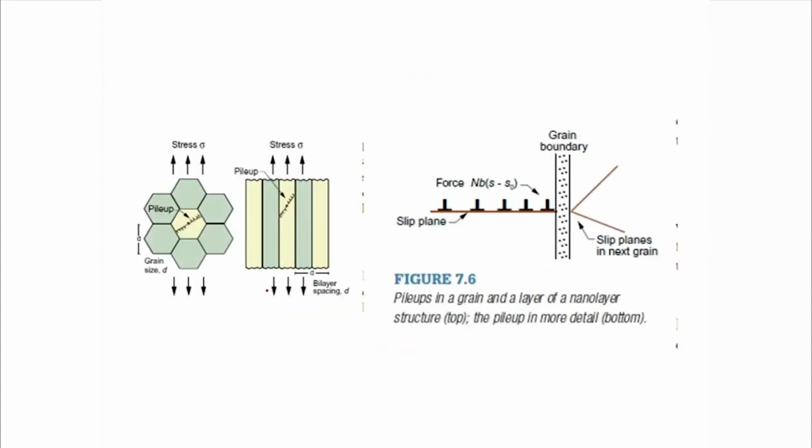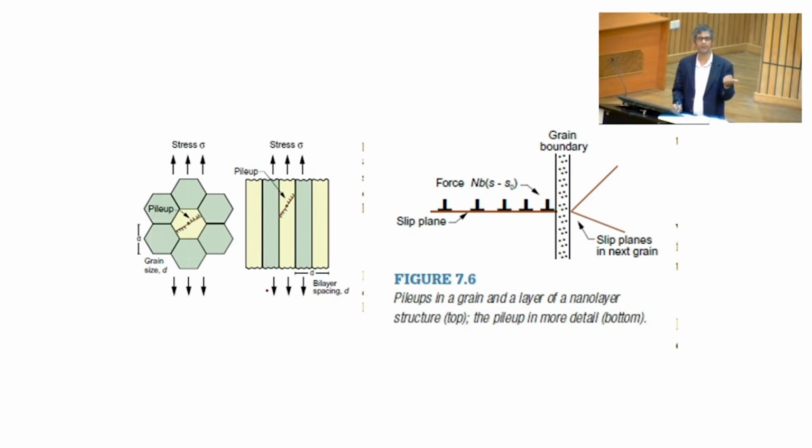Let us shed some light onto it, and then we will stop this lecture. Well, that's very easy to understand. The grain boundary strengthening is because of the pile up of dislocations at the grain boundaries. So this pile up of dislocations means you need many dislocations to be accommodated inside the grain. Then only is the pile up possible, right? If you have two passengers standing in front of a railway counter to buy a ticket, there is no pile up. Only when you have tens or hundreds of passengers, then you have a pile up. But think about it. If you want to create tens of passengers in front of a ticket counter, you need space.